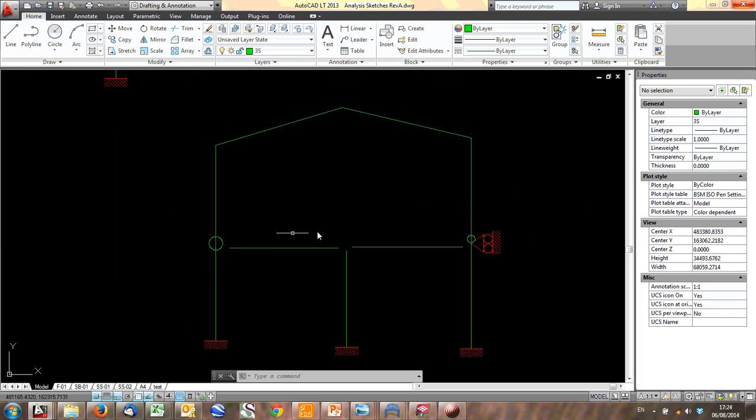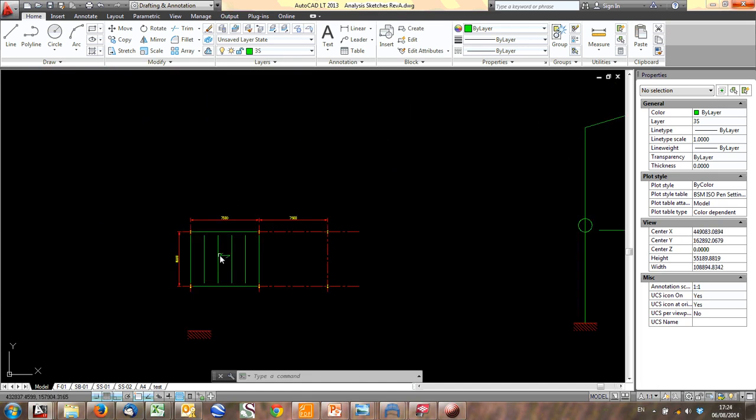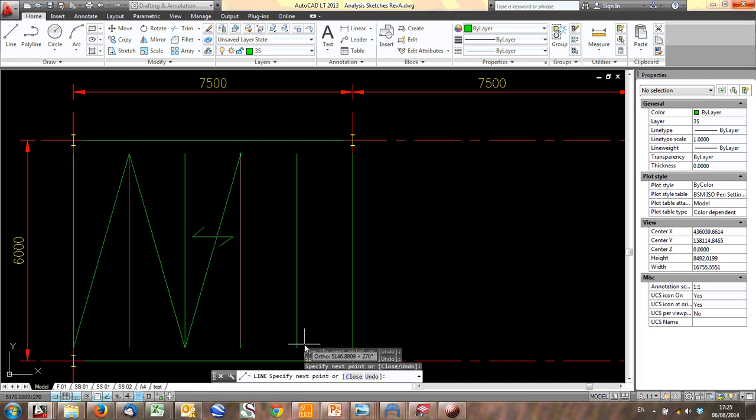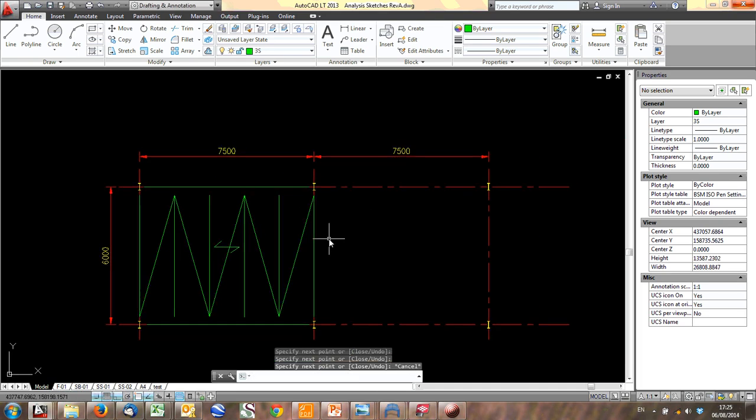Let's say now there's no concrete slab on this thing. Let's say the floors look like that and there's just some grating on top. How do you do that? Well, you've got to carry the load sideways. So you could even brace this whole floor out. And you can make the floor brace the structure. Something like that. And this then becomes a kind of a truss.